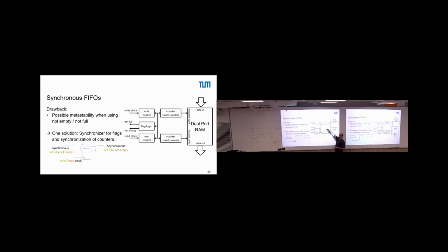And this decision triggers, are we full or are we empty, right? So the write counter is driven by the write domain. The read counter is driven by the read domain. That means these two counters run on asynchronous clocks. So they're driven by asynchronous clocks, and then we form a logic on asynchronous clocks.